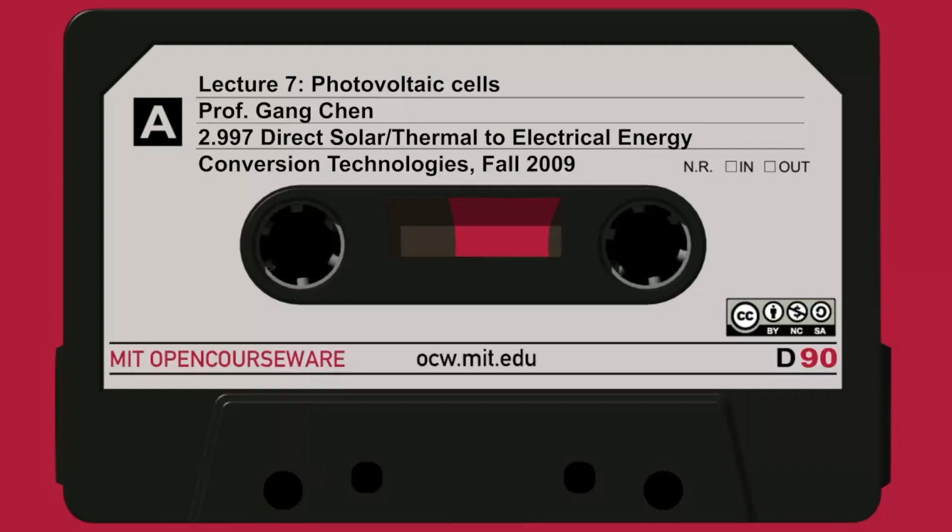This is, say, when you create an electron-hole pair, you excite the electron from the valence to the conduction band. How long they can be kept separate, and after a certain amount of time, they will recombine and give off either a photon, as in a laser or light emitting diode if you want, or give off heat.